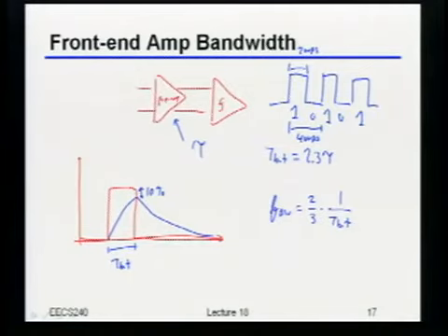So just based on that, you'd already say, okay, if the Nyquist bandwidth is 2.5 gigahertz, then it makes sense that I don't need a whole lot more than that, right? Now, it does turn out you want slightly more than that. By the way, this is just a rough rule of thumb. For your phase of the project, you should feel free to figure out what it really should be. The reason you don't need a whole lot more is that the fastest thing you could possibly be sending from a frequency standpoint is 2.5 gig. So if you don't want to get too much loss, meaning you really want to fully resolve that 2.5 gig, you make your bandwidth about 2/3 of that.